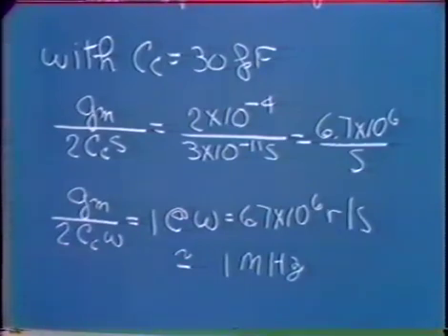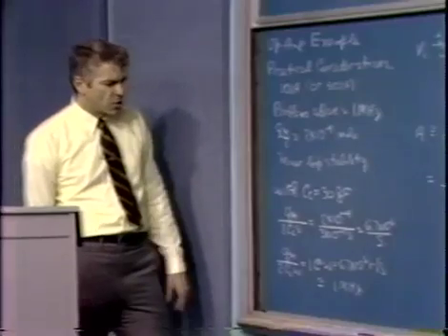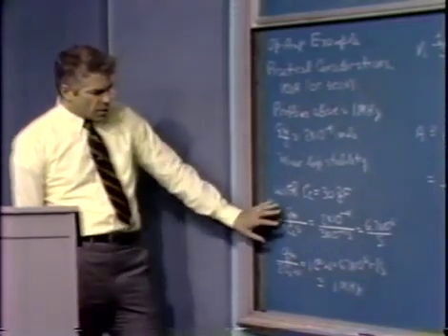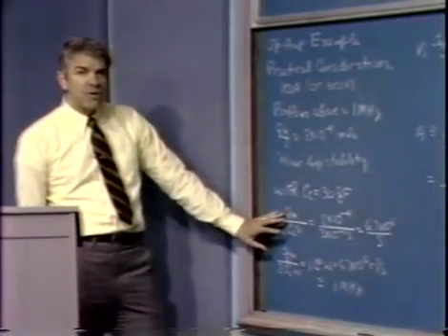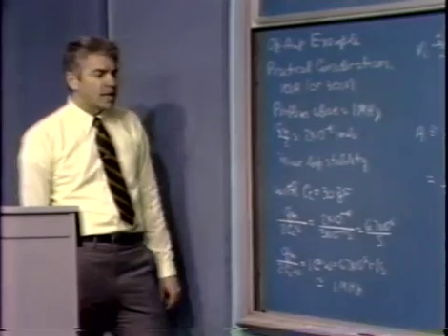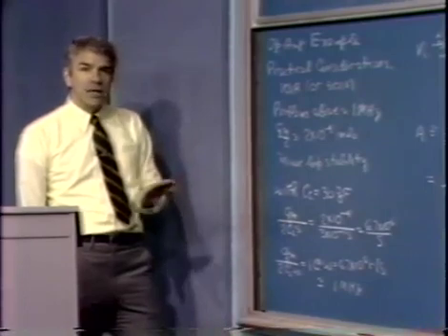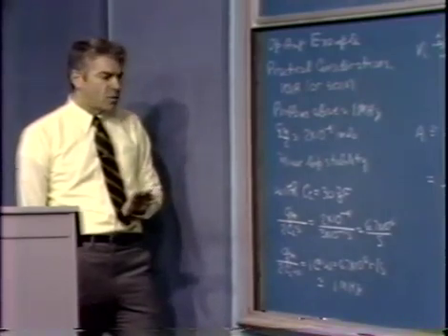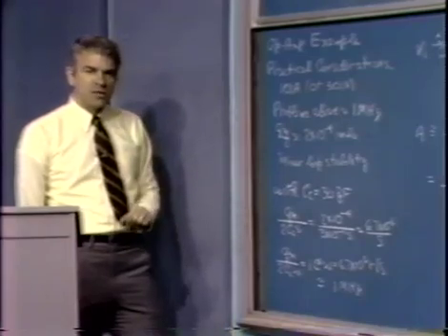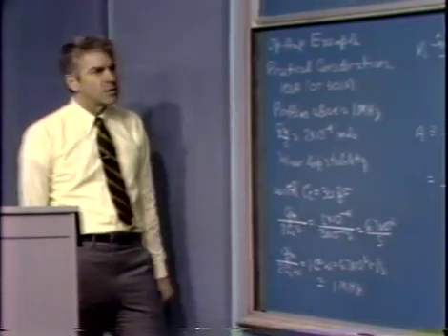And we mentioned that the phase shift problems associated with the dynamics of the PNP transistors that are typically used in this topology are such that we have to constrain crossover to about a megahertz, or else we'll get stability problems. So this amplifier, one that uses a 30 picofarad capacitor, is an example of one that will be unity gain stable. In other words, if we form a feedback loop with f equal to 1 by connecting the output of the amplifier directly back to its input, the resultant configuration should be stable since the major loop thus formed crosses over at about a megahertz.